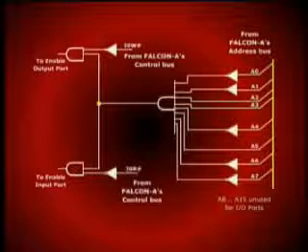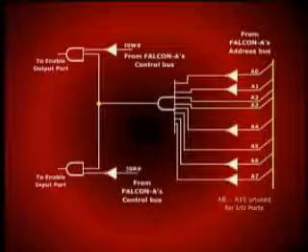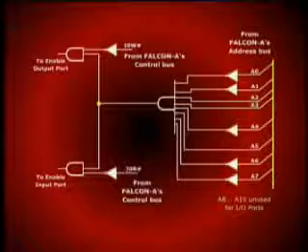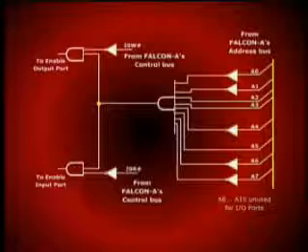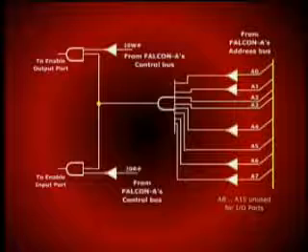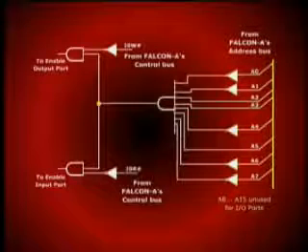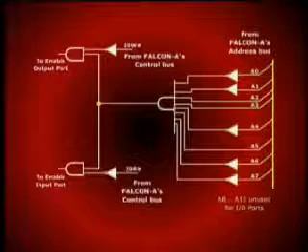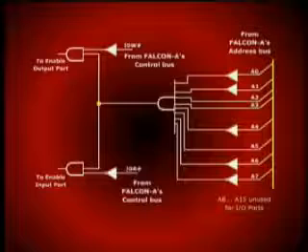The output of this 8-input AND gate is a common input to the next two 2-input AND gates. In the upper AND gate, the second input is the inverted I/O write signal, and the output of this AND gate would go to the enable of the output port. The lower AND gate utilizes the I/O read signal as a control input, and after inversion, it is fed as an input to the AND gate.